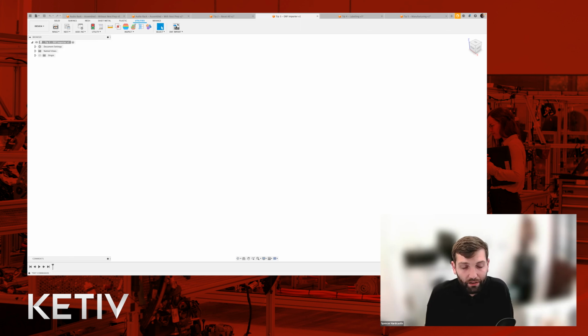and apply a thickness. Now, if I was to do this using native Fusion, I would have to insert Dxf one by one by one by one. It's a tedious and laborious process. So the Dxf Importer allows us to expedite that. So let's give it a go.